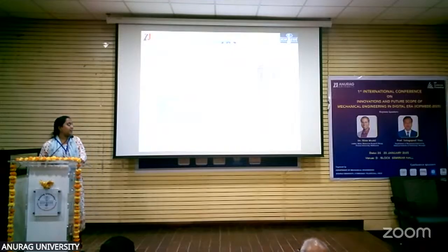So this is our experimental work. First, we have taken 100 grams of plastic raw materials, and then using a reactor, we have heated the plastic materials at a temperature of 300 to 500 degrees Celsius. Then using a condenser, we have cooled the gases obtained at a temperature of 20 degrees. Then we have obtained a fuel of 11.5 to 12 milliliters.